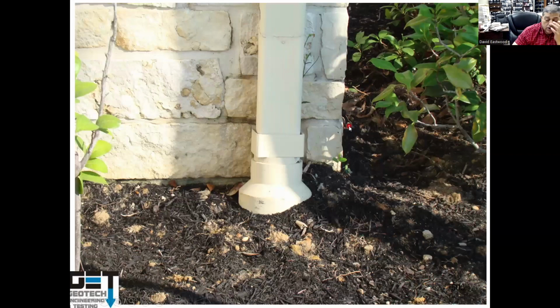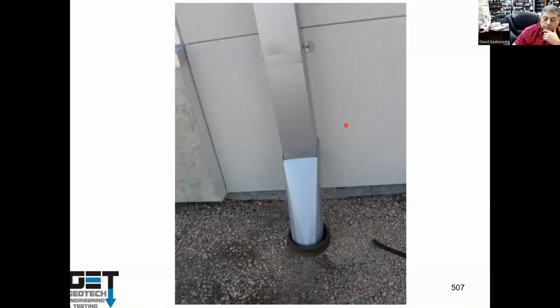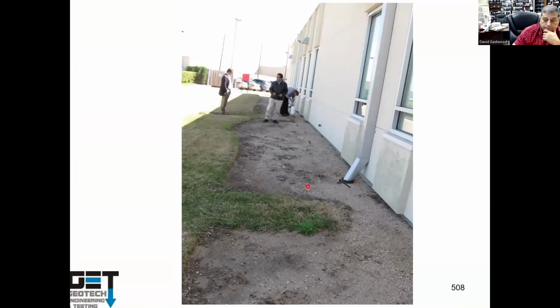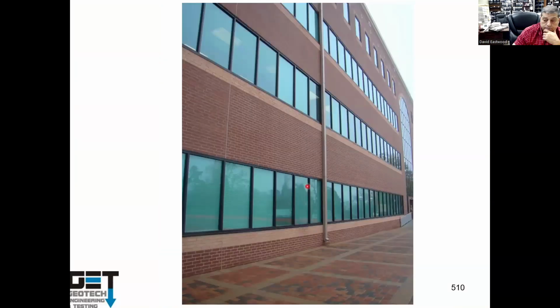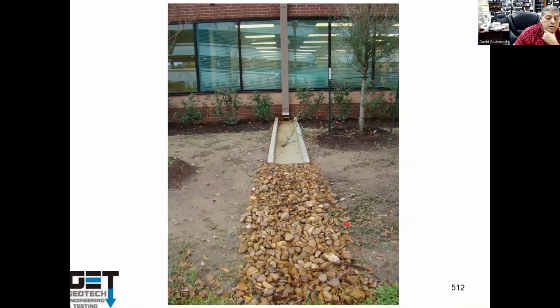You got to take those gutters into an underground drainage system. These are more gutters going to an underground drainage system. These gutters are dumped right in front here in the pavers. Not a good design. It feeds the expansive soil, causes movement. Pavers are permeable. Not a good design here. You get the splash box, get that water away. This is better than nothing, really.